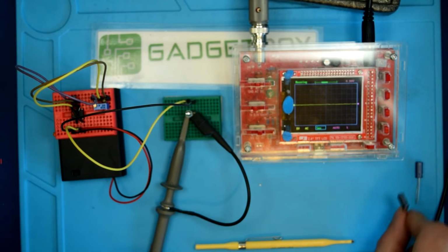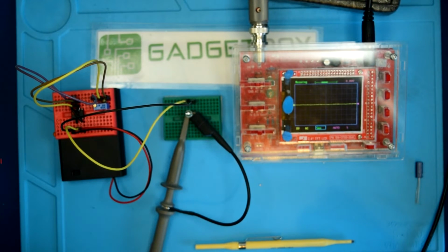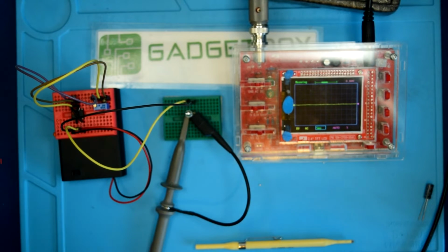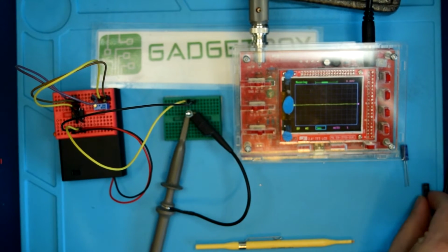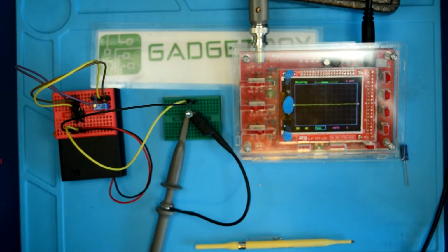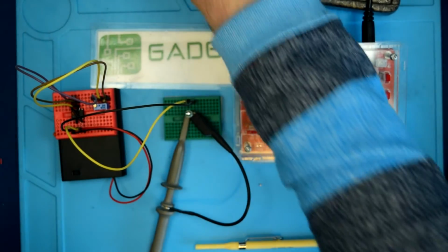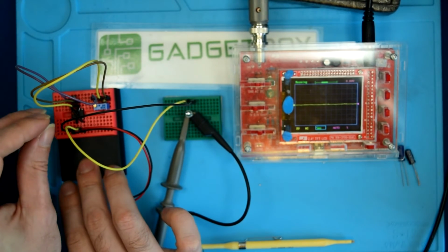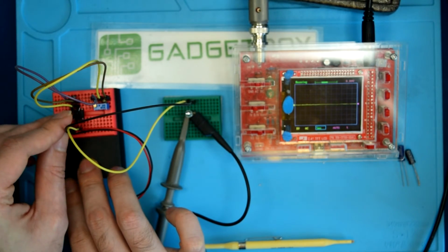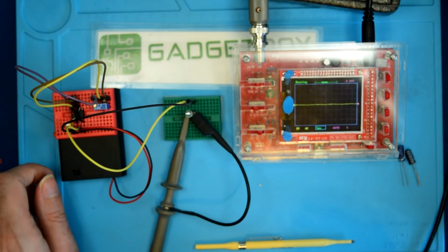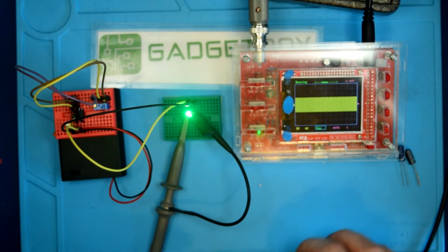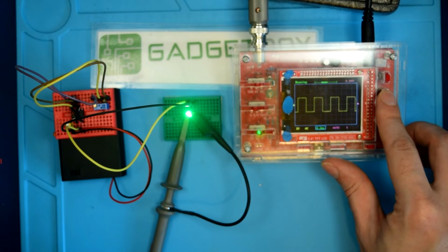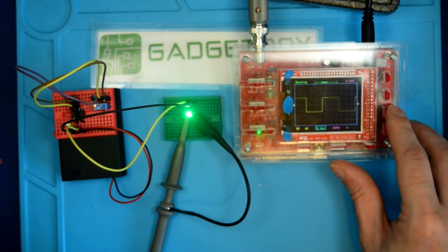Let's go smaller. So let's pull out that capacitor. If anybody's following along at home, I started with a, what was this, 220 microfarad, then I moved down to a 10 micro. Let's move down to 0.22 micro. Now we're going to get up into the kilohertz. So let's turn that back on. Change our time base again to something more compatible with filming.